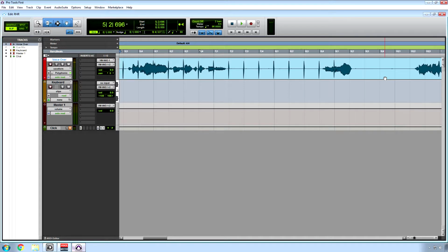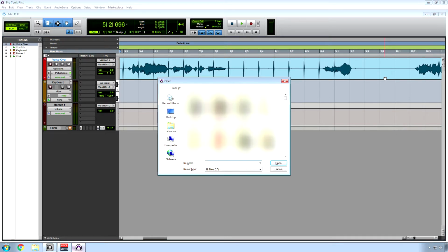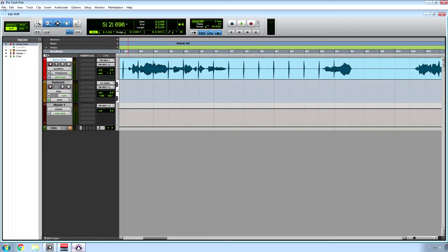If you want to add tracks that are already recorded, hold Control, Shift, and press I. And now I have to blur this out. But this is how you import, and the other way to do this is File menu, Import. It's as easy as that. You can drag and drop files from Windows Explorer. However, they have to match the file type or the project type. Otherwise, it says, nope, I don't like it.